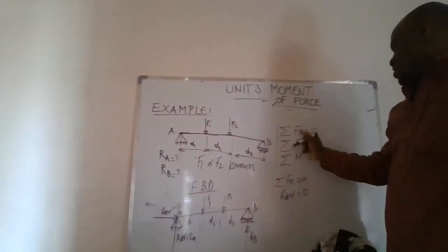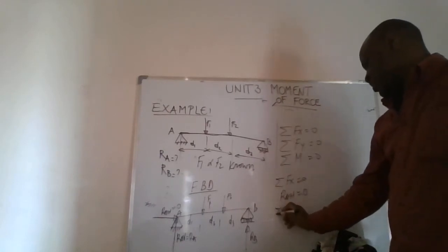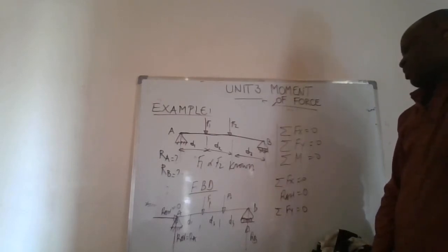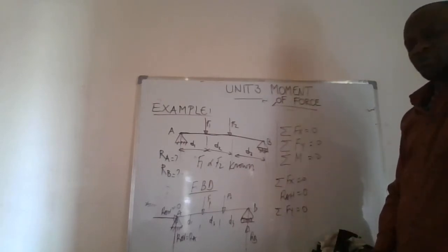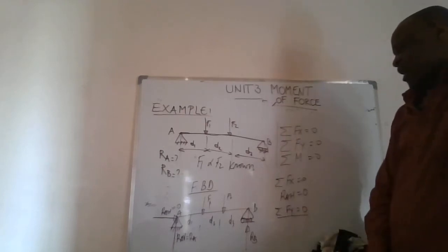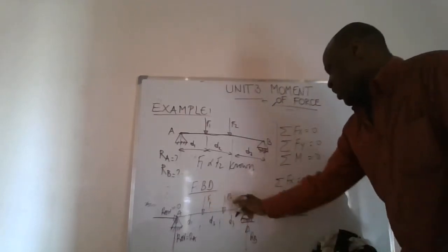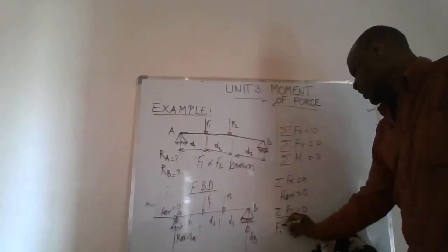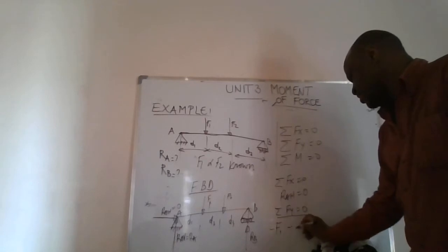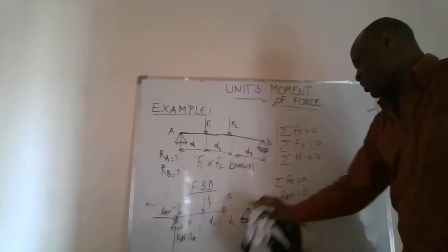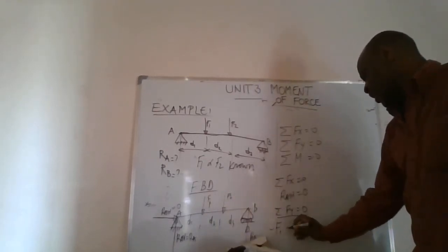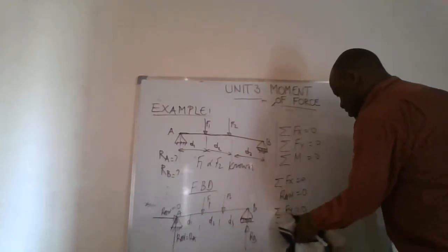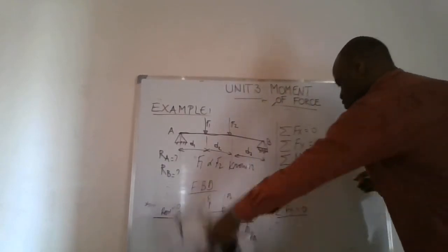Now, that's horizontal. Vertical, if I check with the second equation of the first condition, sum of the forces projected on Y, on the vertical direction, should be equal to 0. Let me look at the forces that I have vertically. F1 and F2 are known, and they are going towards negative values of Y. I can give them minus, or I can give them positive. That's not a problem. Let me keep them. Yeah, let's do this.